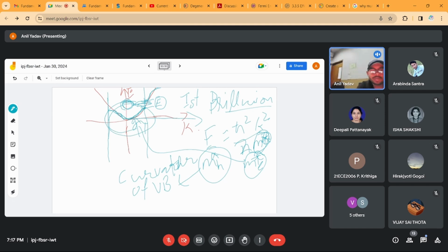Also, what we can see is m* = 1 over (1/ħ² times d²E/dk²), that is, m* = ħ² / (d²E/dk²). This is the relation between the effective mass and the curvature of the E-k diagram.